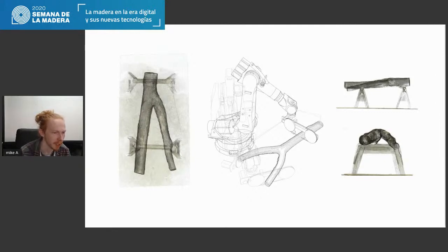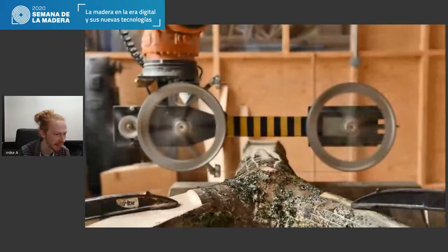So this began again with digitizing, collecting the data of the tree and simulating it into the robot, and figuring out how we were going to get the robot to follow the natural grain. We were studying the grain alignment, the longitudinal direction of the grain, to get the strongest and most complete laminations that we could, which just wouldn't be possible to achieve by hand. To get these perfect thin laminations consistently with a handsaw would be pretty much impossible, I would dare to say.